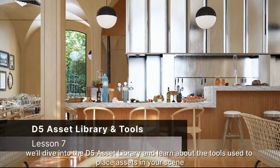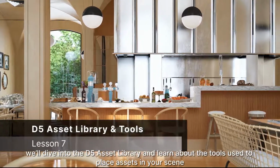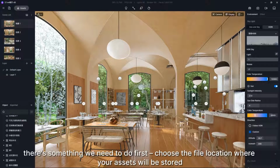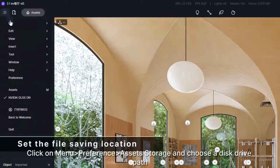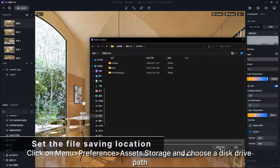In this lesson, we'll dive into the D5 asset library and learn about the tools used to place assets in your scene. But before that, there's something we need to do first: choose the file location where your assets will be stored. Click on Menu, Preference, and then Asset Storage and choose a disk drive path.